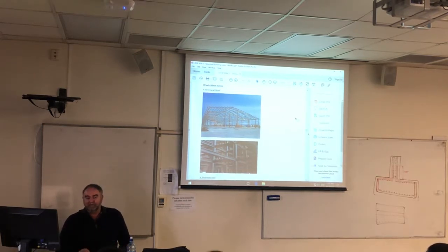Also, when it comes time to putting your drywall on, or what we call in New Zealand gypboard, that doesn't have a time period because once you're dried in, everything's dried. Tin dries straight away. You can fix to it. In a normal domestic build, you could be waiting anything up to 4 weeks for your moisture content of the timber to get down to a point where they can put the drywall on it.